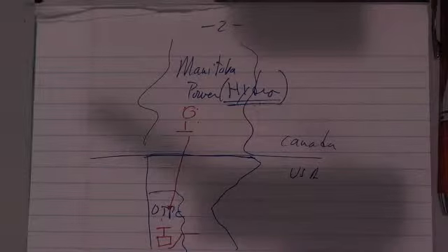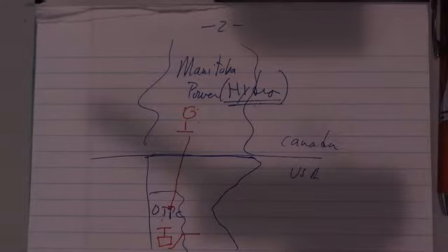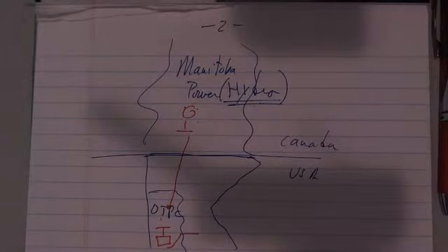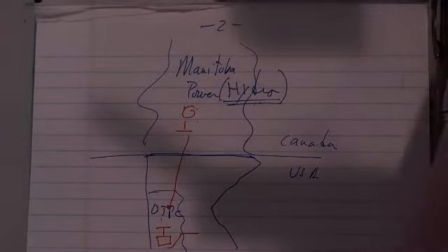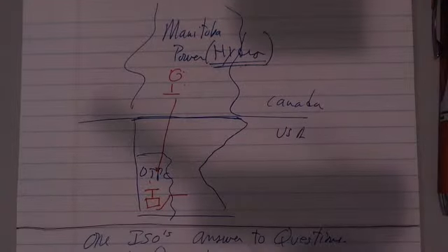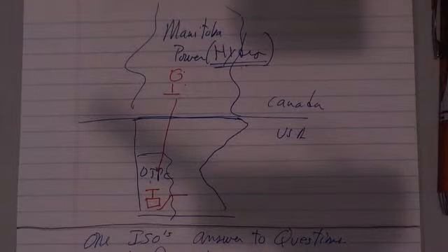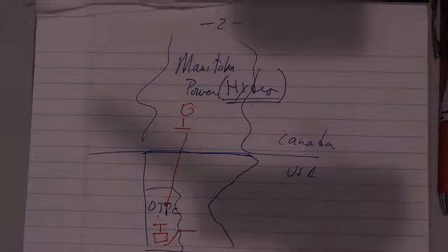The money that is left over. Okay, since LMP is not the same at each bus, then megawatts load times LMP at the load bus, and we seem to have a dying pen here, is not equal to megawatts generation times the LMP at the generator bus. Now this is what he pays, and this is what he is paid. And if they're not equal, there's some money left over.